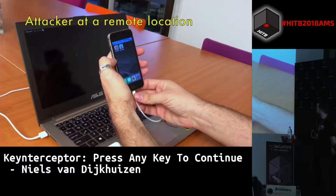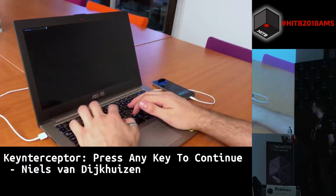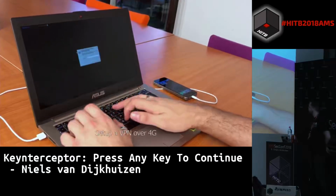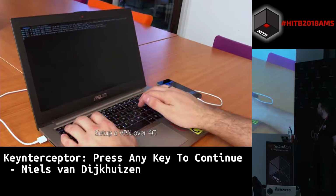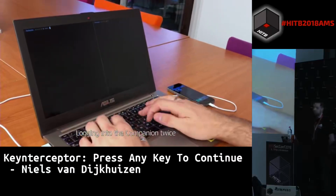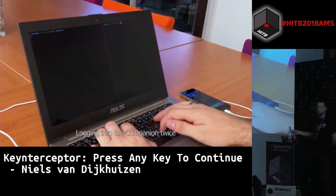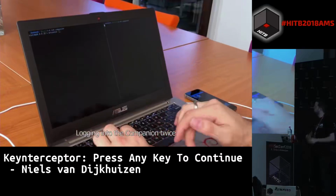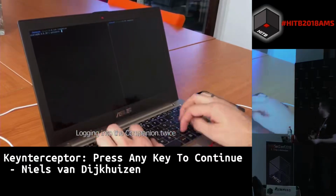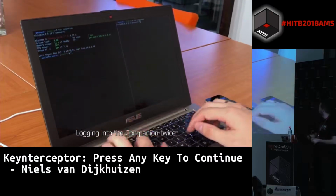So at another location, we hook up the computer over 4G with an OpenVPN connection. Once we're done, we have the ability to log into the companion and start a listener. We'll start a listener on the left side, and we'll start the keystroke sniffer on the right side, because the keystrokes are sent over 433 MHz to the companion.